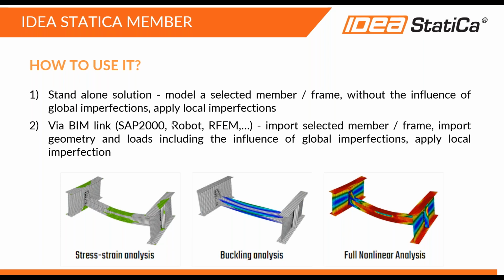Just use the BIM link. So we import all the data, all the geometry, and all the loads from these softwares, of course, including the global imperfections from the global model, and we just apply this local imperfection on the member. So that's almost no work after all.